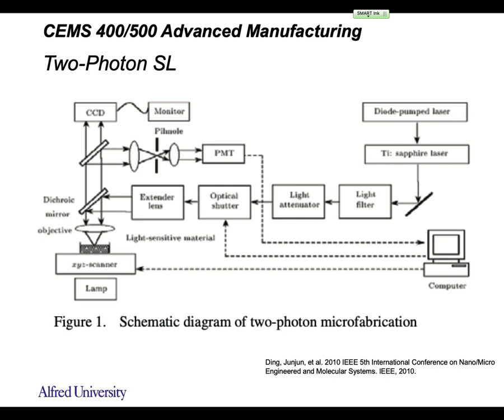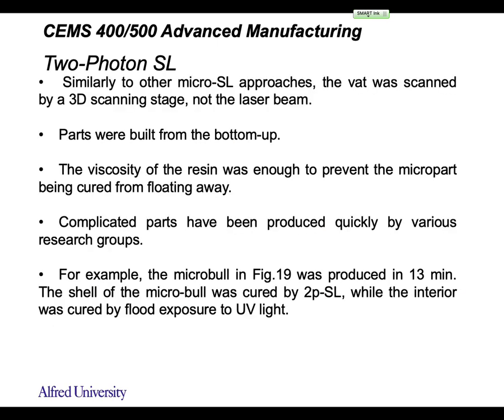And this stage has to have a really high resolution, right? We had a nanoscale stage, nanoscale resolution. I think it's one nanometer in X, Y, and Z directions. So it's a piezoelectric based stage. Right? So that means the total distance it can move is quite limited. I think it can only move up to 50 or 100 micron, not even close to 1 millimeter.